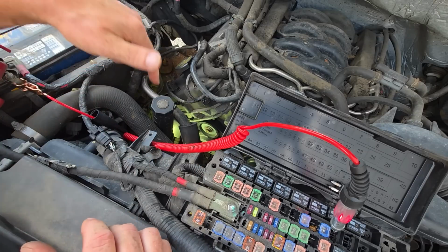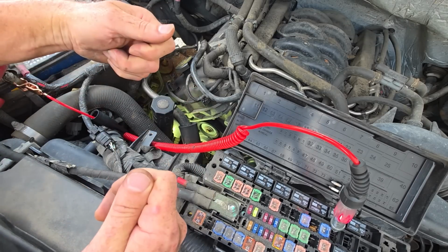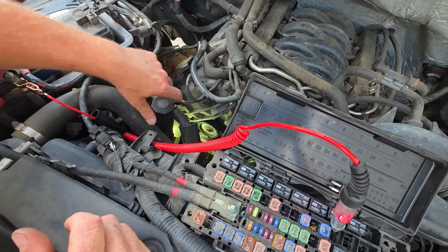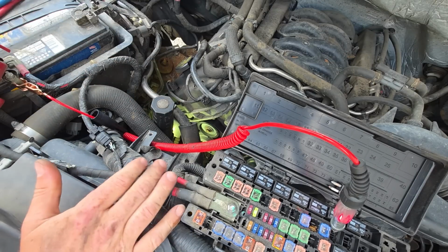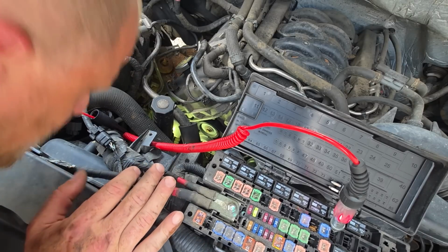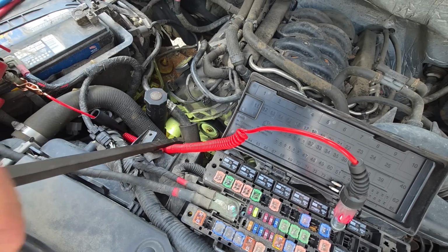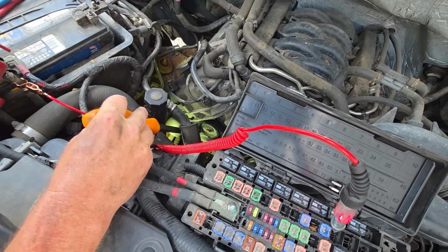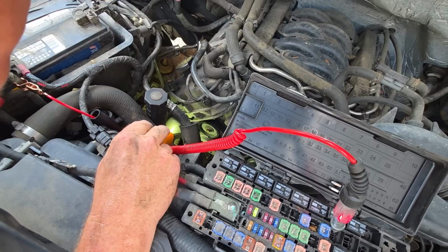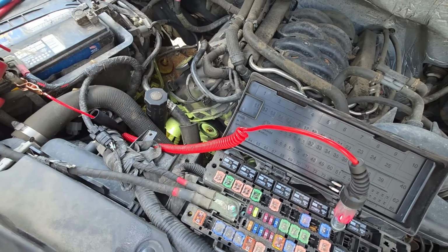So just so everyone knows, I'm going down to where that connector is and I'm going to unplug it and then pull it up to where we can maybe see it a little bit better. That's the only thing I can do because it lives in a really, really difficult place. I'm not going to be able to show you at the same time I do it. So I'm going to actually use my pry bar, push on the part of the connector that's up near the pulley, make sure that part is okay. Yep, a little tiny flicker. Yeah, but I think it's on the connector itself.